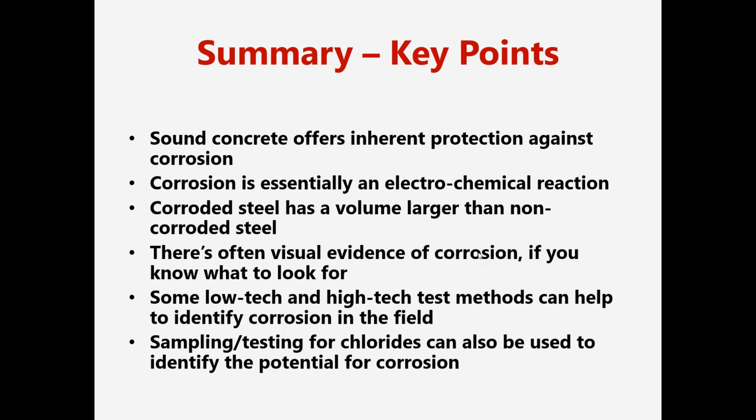You've got electrons moving around, different forms of iron oxide being created as the steel corrodes and oxidizes. Corroded steel has a significantly larger volume than non-corroded steel, which is one of the reasons why you get spalls and delaminations and things like that. Those tensile stresses build up in the concrete when that steel is expanding.